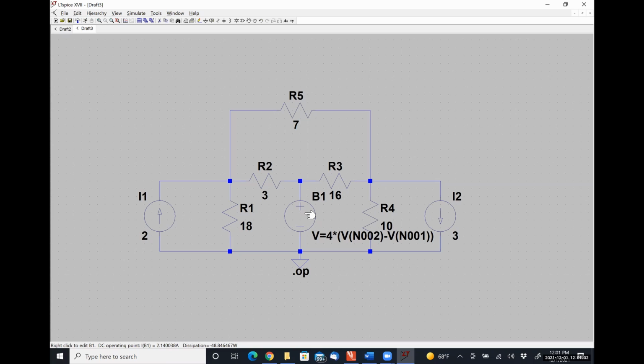Is there a way to add dimension to this program, as in adding a length to your wires, size, that way you can account for internal resistance of wires? I'm not sure. How I've always done that is literally just putting a resistor there and setting the value of the resistance based on the math that tells me what to do.